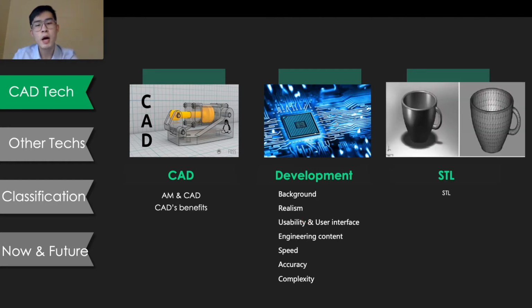Well, it is quite possible to directly manipulate the CAD file to generate the slice data that will drive an AM machine, but this would mean every CAD system must have a direct slicing algorithm that would have to be compatible with all the different types of AM technology. Alternatively, each AM system vendor would have to write a routine for every CAD system. Apparently, both of these are impractical.